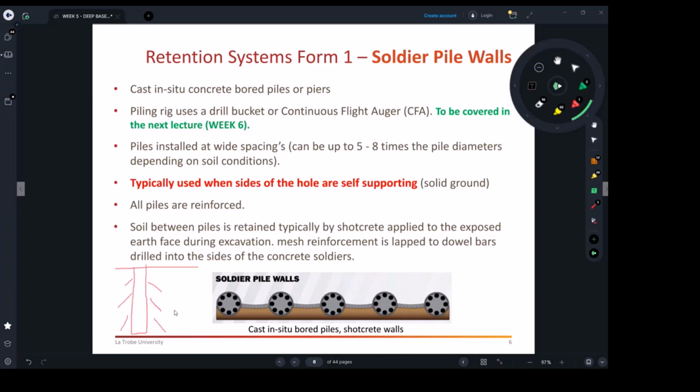It is widely used, mostly used, where the soil conditions are not stable and things will keep collapsing. So what we do in this case, especially when we go beyond 3 meters deep piles, like you can see many residential applications, they use this process, just the piling ring or the drilling bucket, because if you're excavating just 3.5 meters deep piles, but once you go to 9 meters deep, definitely things will collapse.